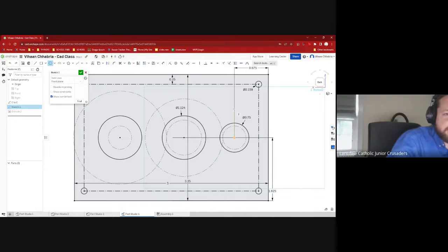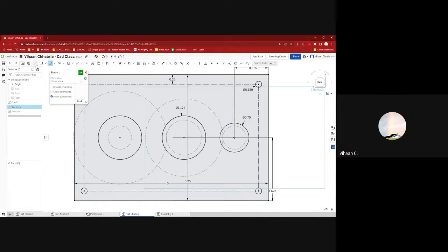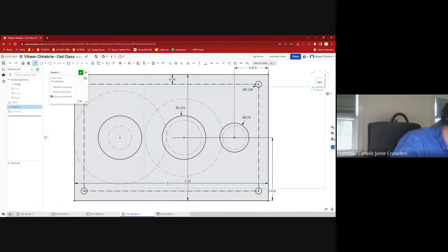I would try a line. Oh, okay. A line? Yep. You'll see why. Don't start it at the center. I mean, you can, but I'll show you a trick. So delete that for now. And draw a line out like in space somewhere, like way off the plate. Not even attached to anything. Okay. Now put a dimension on that line.